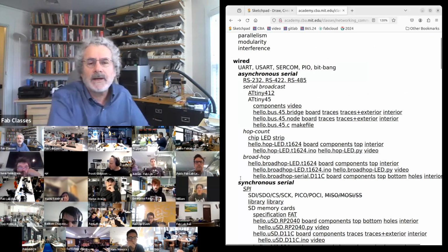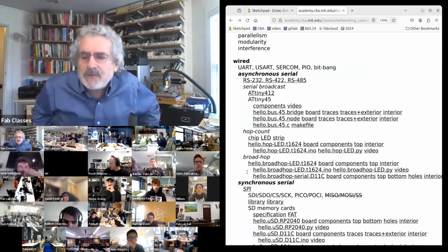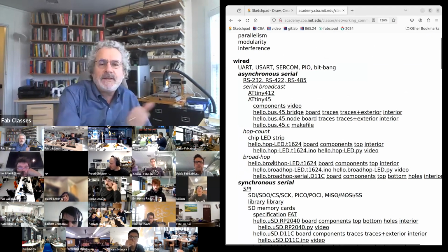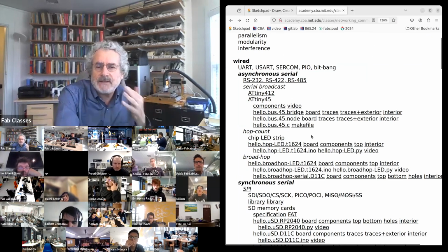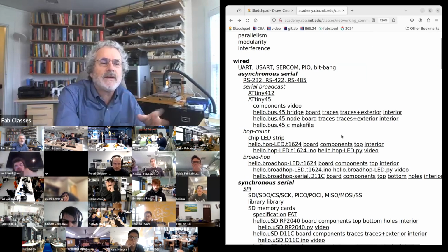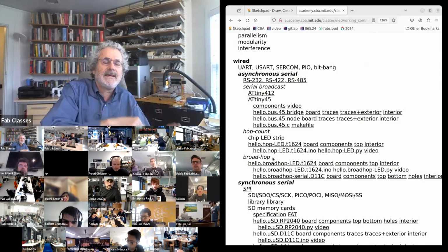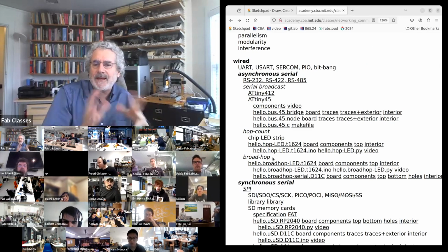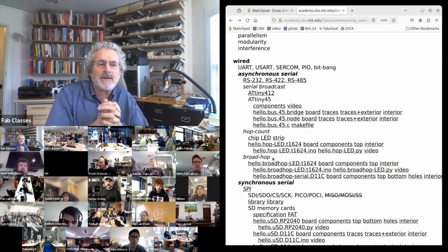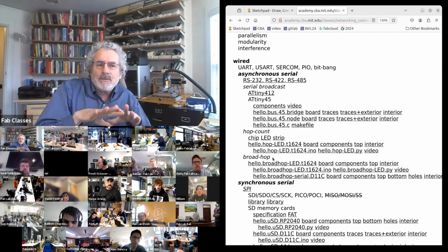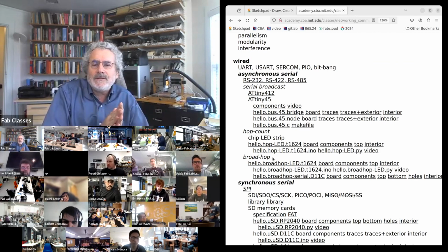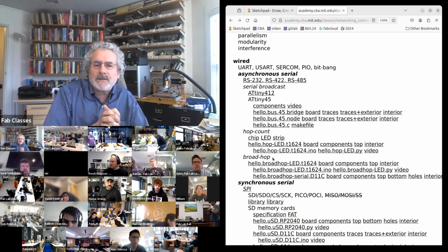So that's a serial bus, simple, straightforward, but needs addresses. Hop count eliminates the addresses, but has some overhead. And broad hop is a combination of broadcast and hop count that has the best features of both. And so this is all you need already for this week's assignment.